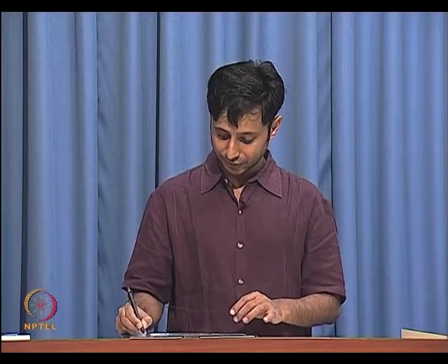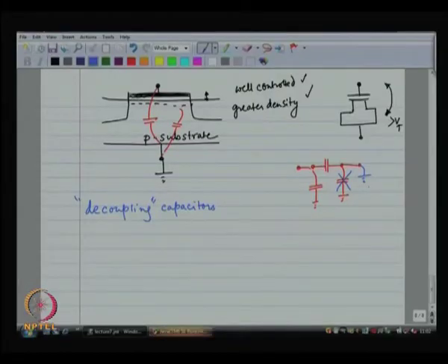This disadvantage is not there, because it is a capacitance to ground. The value of the capacitance is not very critical, because it is a decoupling capacitor. You just want some large massive capacitance over there, and you get great density. You just have to make sure that you have more than a VT between the gate and the drain and source, right. So this is very routinely used in decoupling capacitors. For other applications, if you want a floating capacitor, beware.